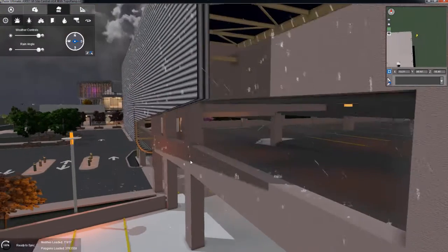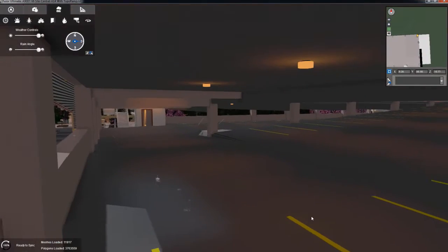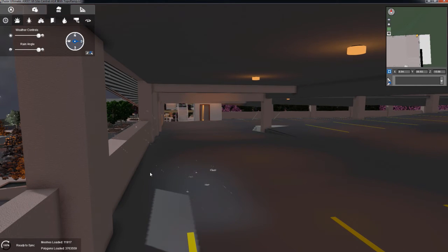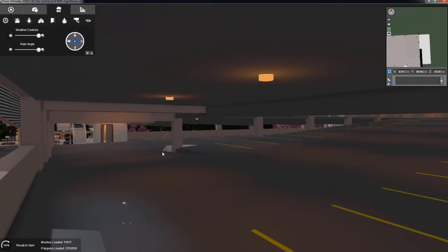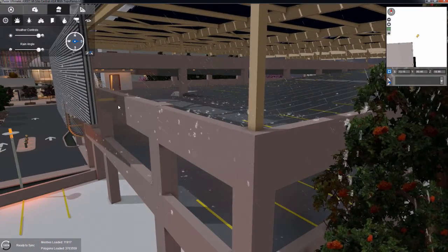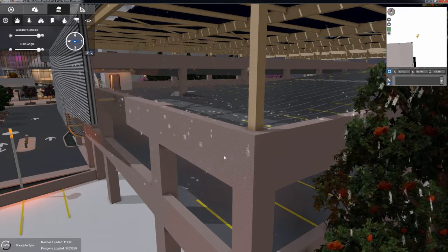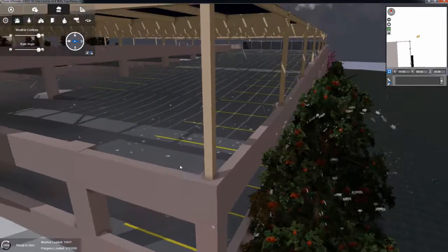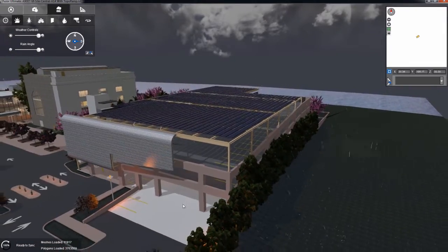You also notice that the shield on this side is actually blocking it from coming in. But what this tells me is if I have any parking or otherwise on this side, it's not really feasible to move the spaces, especially in a parking structure where you have a lot of tight tolerance. So what I can do to mitigate that is I can actually add an awning to basically come out from this side, and that should bring the rain angle back to where this edge is. And that's a really useful tool, especially if this is the kind of weather that you're prone to.